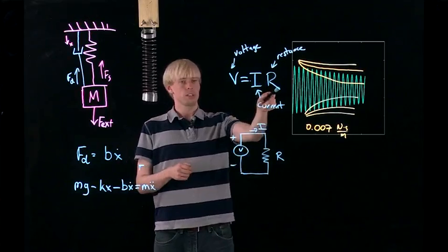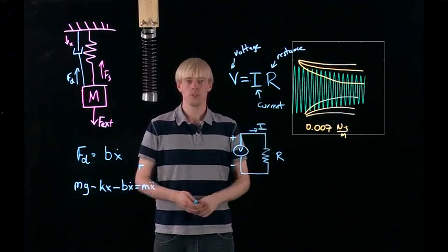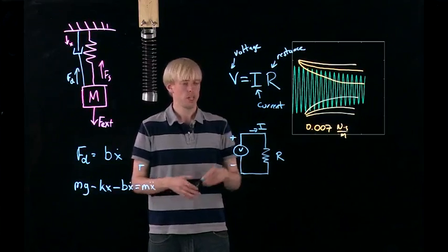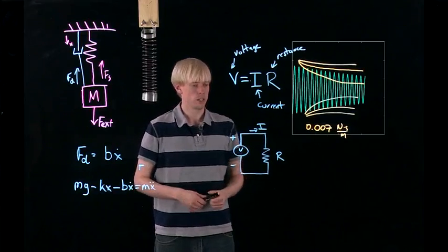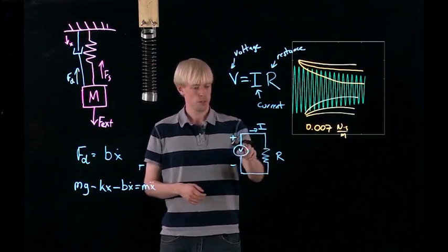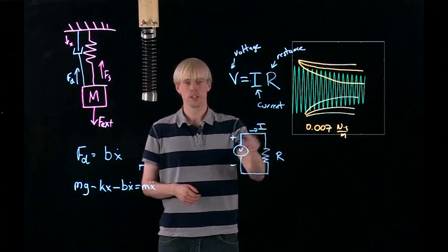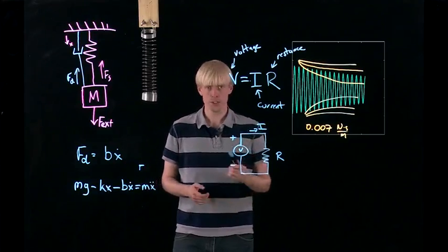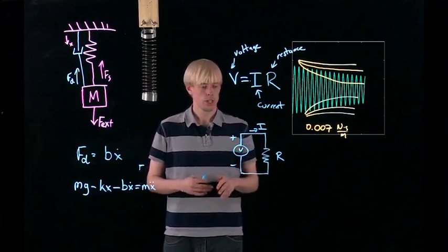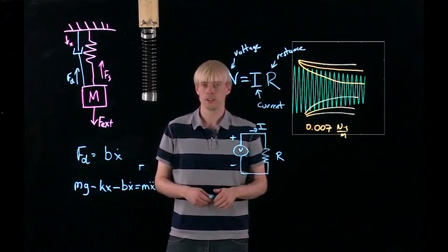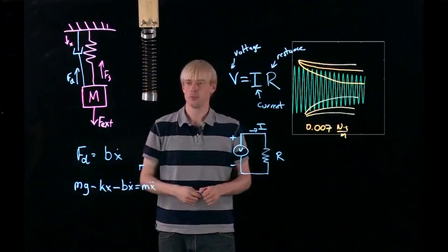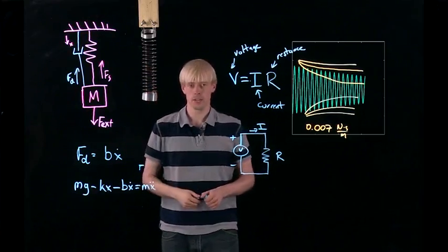Now, as you can see, this is a linear relationship, very much similar to the viscous damping and the spring constant system that we have found. And in a way, they're all sort of related. So to test this out, we need to measure both the voltage and current in the circuit. To do this, we're going to use 2 multimeters. Multimeters are generally a good way to measure any sort of characteristics in the circuit, and it's pretty necessary because you can't just get a ruler to measure out distance or anything like that.